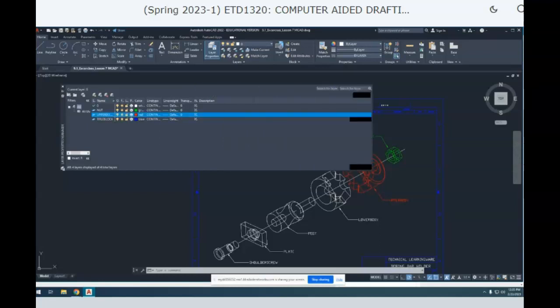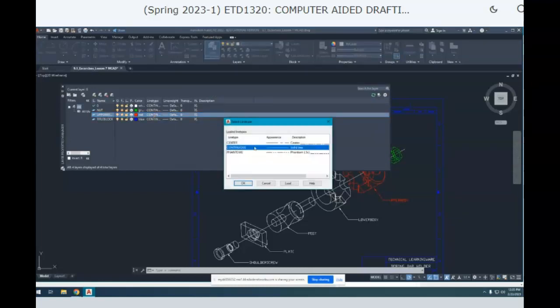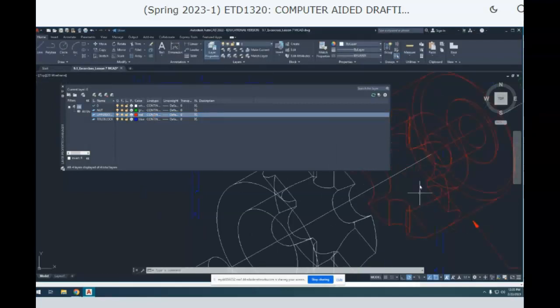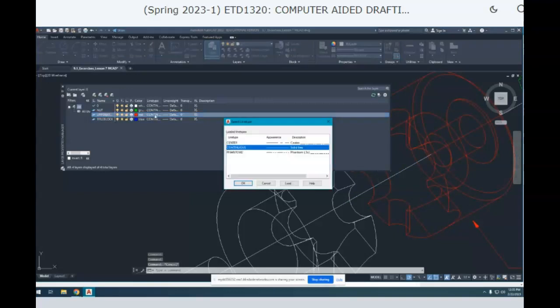Other parts, let's stretch this open. There's a lot of other fun stuff in here. There's line type. So if you want to choose a different kind of line type, here's an example. This should be a center line. So if you change that, you can change that line type, but we don't have a center. So you have control of different kinds of lines. There's only 3 loaded now.